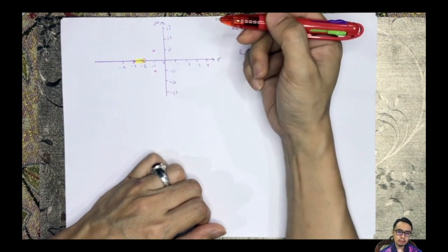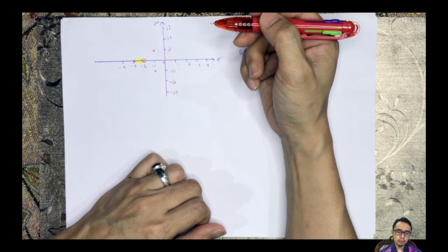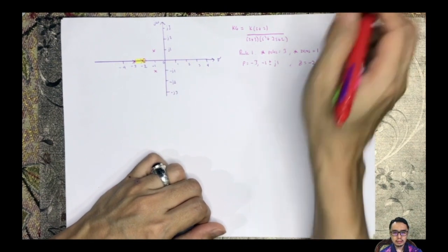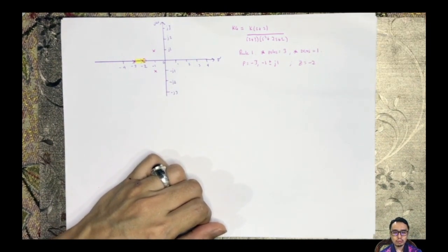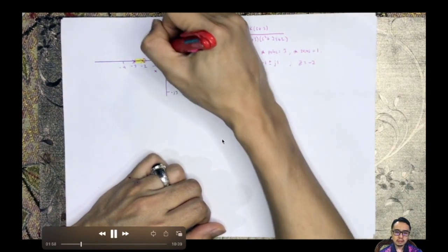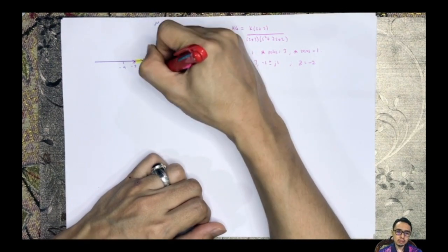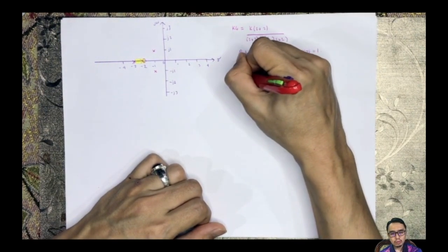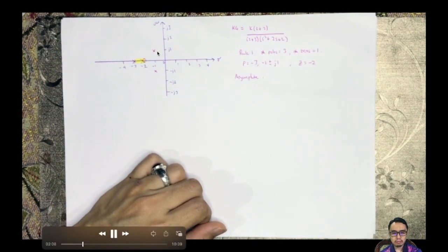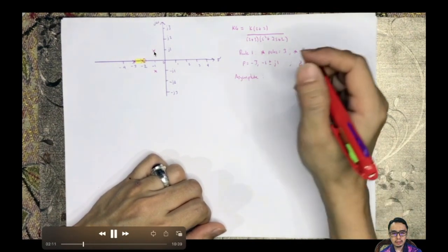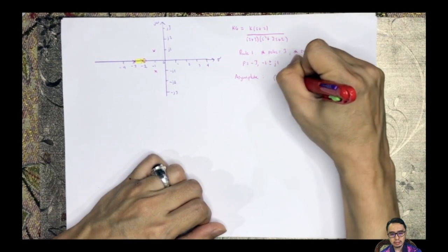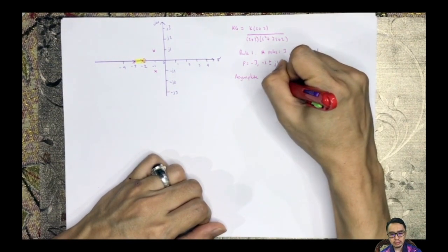So that part is easy, where the locus will start at the pole of minus 3 and end at the zero of minus 2. But what would happen in the case when we have poles at minus 1 plus or minus j1? So we need to calculate the angle of departure. We don't have the idea yet. But for sure, the end of the locus will be at zeros at infinity. So you have to calculate the asymptote.